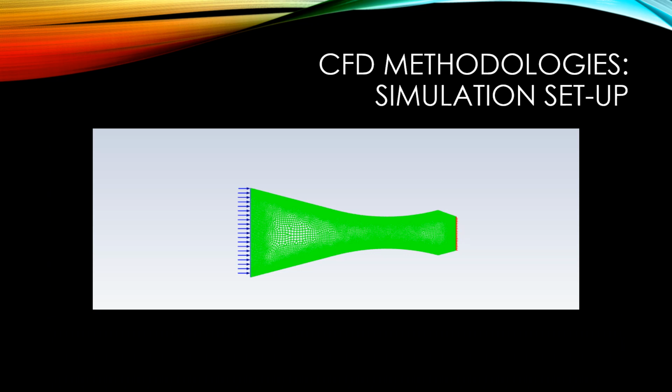Concerning the solution setup, I set my inlet temperature at 461 Kelvin. The inlet pressure for the air was 405.3 kPa. The outlet temperature was set to 1,123 Kelvin. Airflow was set to 4.288 kilograms per second, and I was really looking for pressure and velocity contours.